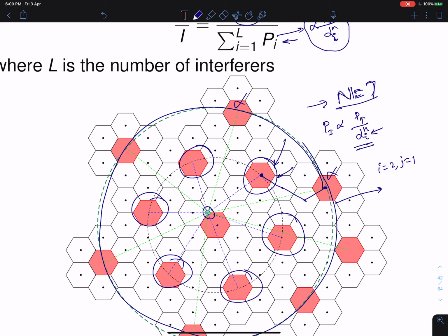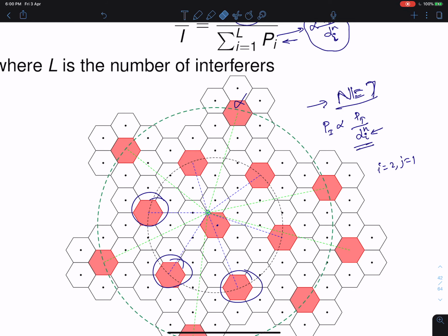Okay, so this is a wireless scenario. Maybe you might sometimes have a direct line of sight path from your mobile station to some other interfering base station, and for every other base station maybe some obstacle has come in between, and so in those cases, that's for an accurate estimation of powers from all the interferers. So for our analysis, I'm going to ignore the tier 2 interferers, and we'll try to mathematically analyze or come up with an analytical expression which we can use for our computations for tier 1 interferers.